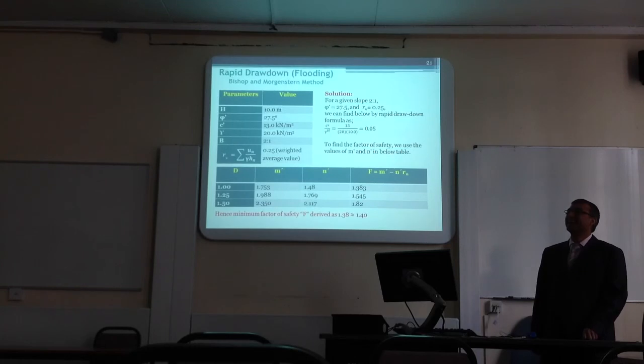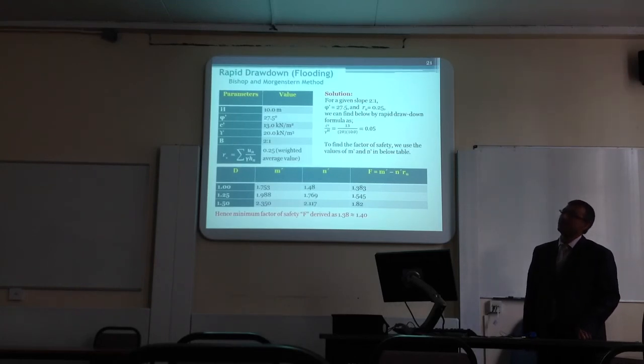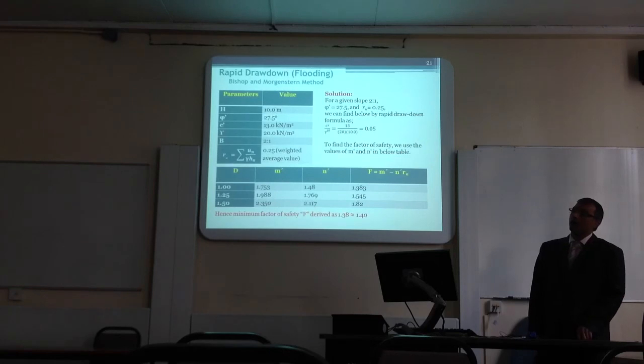Sorry, I was just going to ask, I can see how applying the deterioration model to a newly constructed embankment will work. How would it be applied to an existing embankment? How do you know how far down the weathering cycle you are and how much it's deteriorated? Well, when you come to it?